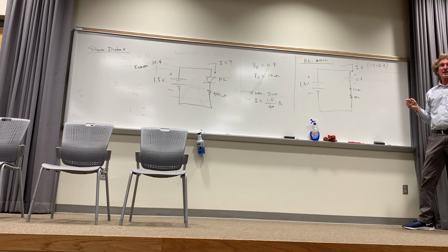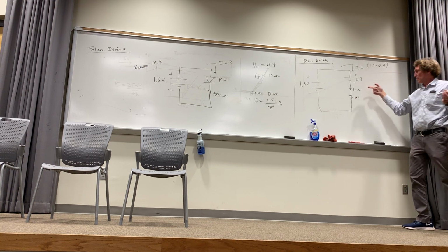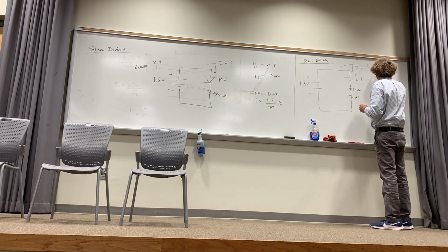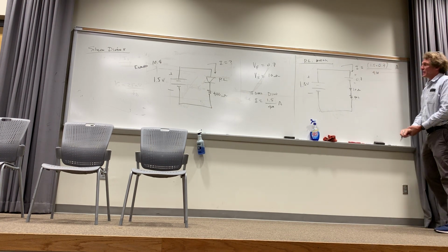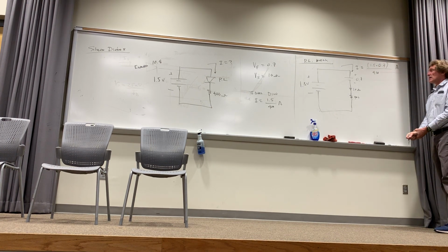Now what do I divide it by? Really, 410 ohms. And that would be the actual current. It's going to be a lot less than that. Right? It's 1.5 minus 0.7, so it's 0.8 over 410. So just about half, isn't it? That's a real circuit, instead of a forward bias. I'm trying to just show you this. I'm trying to incrementally build on this one. That's how a piecewise linear diode would be analyzed. Okay? In a simple sense.